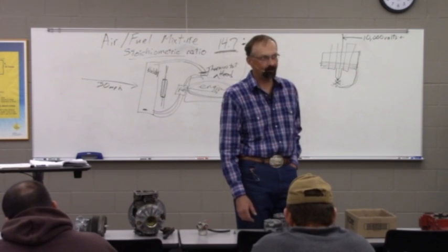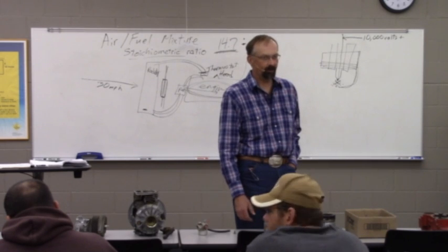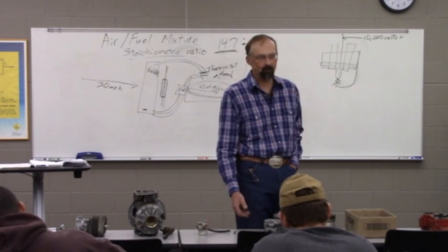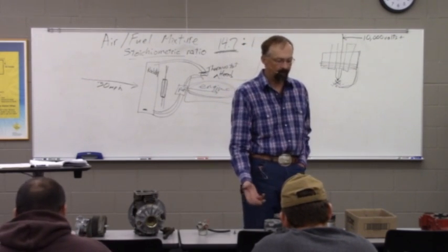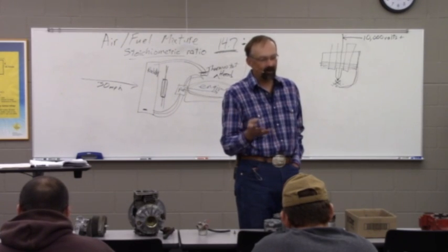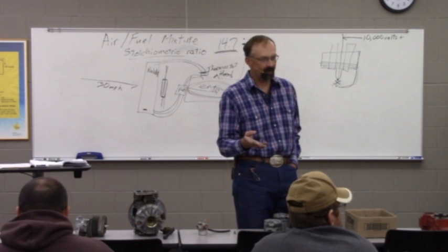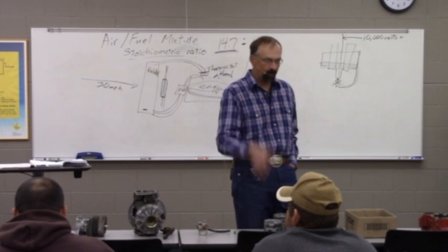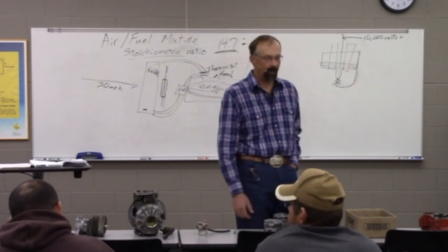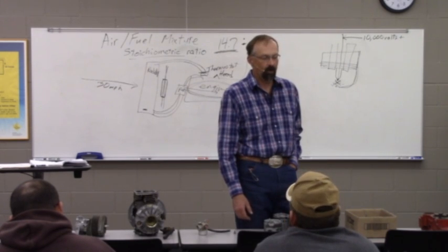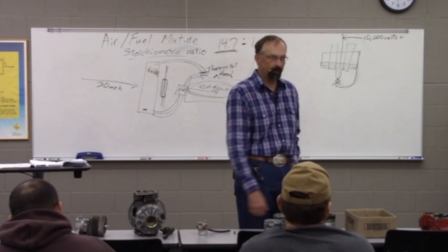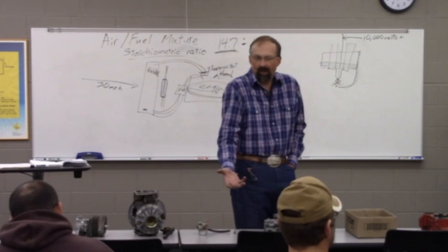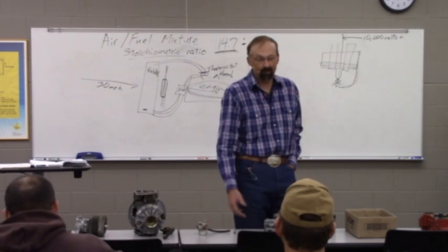But we've probably seen half a dozen engines that had been running standard Rotella T4, the mineral, and all of the engines I'm thinking of didn't go to Rotella T6, they went to AMSOIL synthetic. But with the AMSOIL synthetic, they were burning oil like crazy. They were having to add 2 or 3 gallons between oil changes. And after converting them back to the T4 Rotella, it took 2 or 3 oil changes before they quit burning oil. I don't have a great explanation for why, but that's what I've observed.